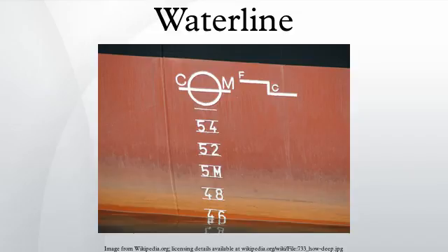The winter load line is 1/48 of the summer load draft below the summer load line. The tropical load line is 1/48 of the summer load draft above the summer load line. The freshwater load line is in amount equal to Δ/40T centimeters above the summer load line, where Δ is the displacement in metric tons at the summer load draft and T is the metric tons per centimeter immersion at that draft. In any case where Δ cannot be ascertained, the freshwater load line is at the same level as the tropical load line. The position of the tropical fresh load line relative to the tropical load line is found in the same way as the freshwater load line is to the summer load line.